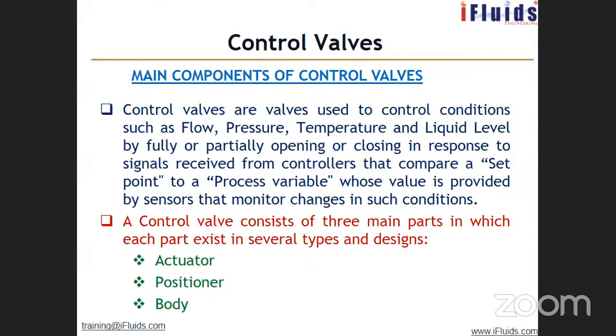The fluids flow continuously, and there are process variations happening, and the individual equipments have their own operating characteristics. So there is bound to be variation in the process parameters. So these control valves try to reduce the variation. That's all. It's not stopping it from deviating from the fixed value, but it allows minor variation around the set point.